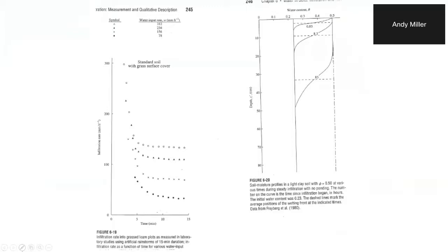So this is actually not soil moisture depth, okay? This is basically infiltration rates for 4 different water input rates. So some kind of sprinkling experiment was carried out. And over here, you're going to see the downward transport of moisture within the unsaturated zone. But here, you're just looking at the infiltration rates. What they're showing you is really 2 things.